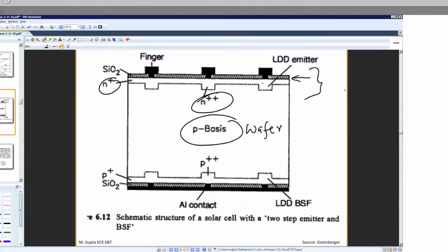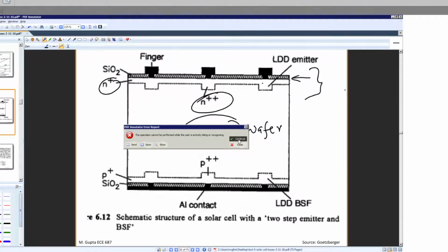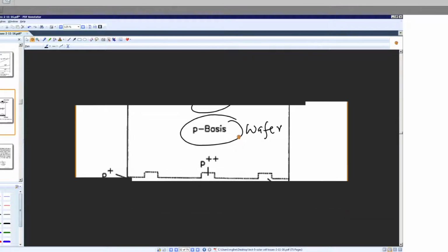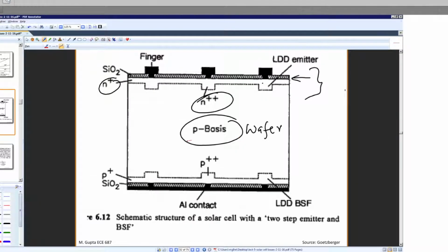So that's why they make these holes and make contact, and there is enough room that carriers can still travel and get collected. But that's where the design comes in, how far this separation should be, and that's where software simulation is run to find the spacing, or what percentage of area the metal should make contact. You have a choice of making 100% or you can make 5%.